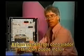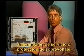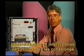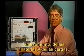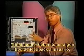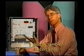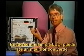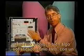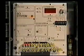Also built into the general plan of the controller might be service disconnects or overvoltage protection, disconnects and circuit breakers for your array connections, your battery connections, and your load connections. And finally, you should have some sort of feedback to the user, some sort of visual display of at least voltage and perhaps current as well. It can be as simple as some LEDs or a simple meter that goes from green, yellow to red, or it might be as sophisticated as shown here with a digital display that might show battery voltage and array current and load current.